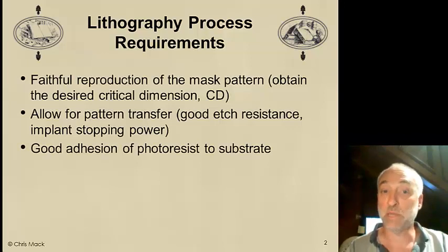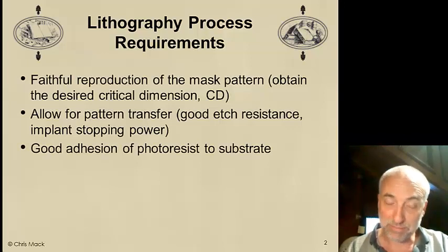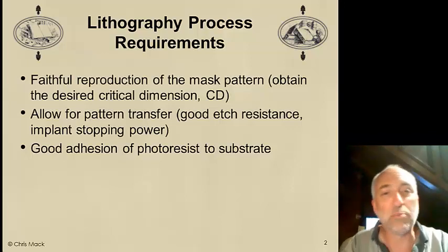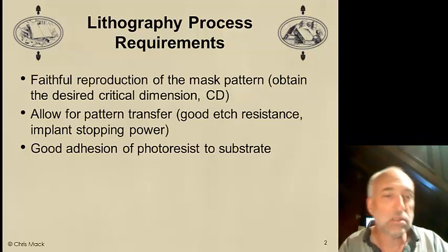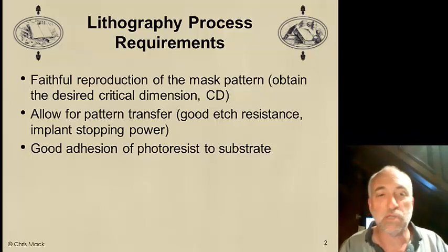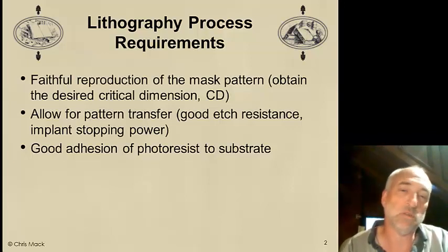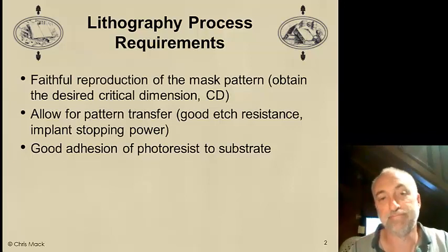The photoresist must stick to the substrate. I've seen plenty of beautiful resist patterns that were imaged on the wafer only to peel off during some subsequent processing because of lack of adhesion of the photoresist to the substrate, in which case all those beautiful patterns go to waste.